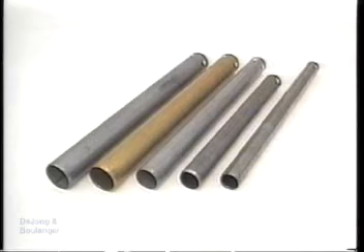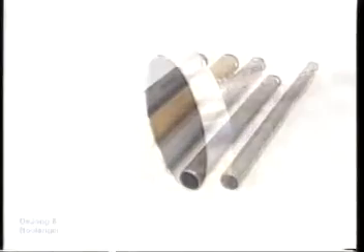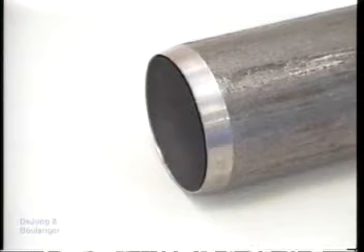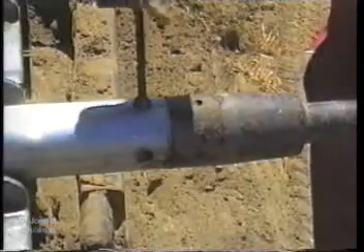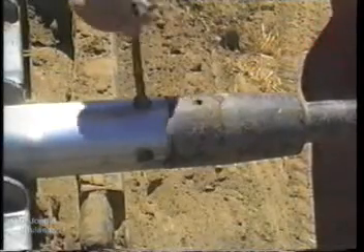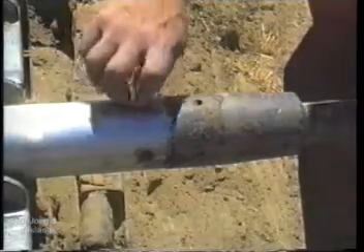Thin-walled Shelby tubes come in diameters from 2 inches to 3 inches, commonly have a length of 30 inches, and may be made of galvanized steel, stainless steel, or epoxy-coated steel. Tubes of much larger diameter can have difficulty retaining the sample. The lower driving end of a thin-walled tube is beveled to a cutting edge, creating a slight inside clearance. The upper end is attached to the drill rods using 4 hex screws and an adapter.